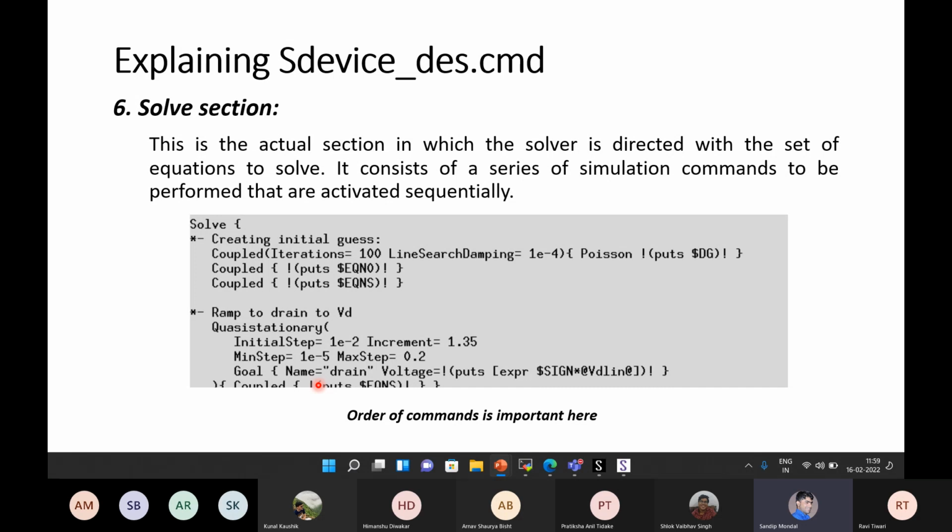So step by step you increase and find the capacitance value. Here also, in a similar way, you can change your voltage sweep in a particular step. Then you can measure your current after each step. At each step you are fixing your parameters and seeing the output you are getting. This is similar to what we see in the CV curve also.